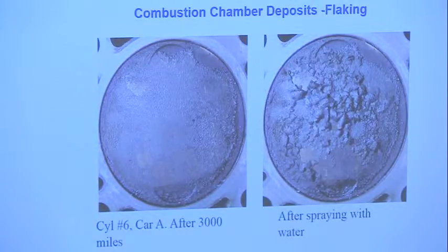As you're watching, sometimes these deposit flakes could actually jump off. It's as if they are under some kind of tension, like a spring, and you suddenly release it and it jumps off. So you can imagine if this had happened overnight and you start the engine, one of these flakes could come and lodge itself.